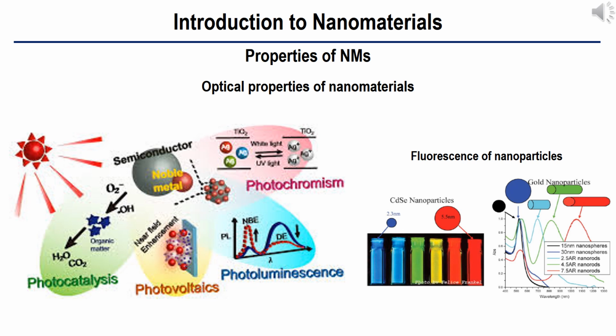Nanomaterials have structural features in between those of atoms and the bulk materials. While most microstructured materials have similar properties to the corresponding bulk materials, the properties of materials with nanometer dimensions are significantly different from those of atoms and bulk materials. This is mainly due to the nanometer size of the materials. The nanometer size effects give a large fraction of surface atoms, high surface energy, spatial confinement, and reduced imperfections, which do not exist in the corresponding bulk materials.